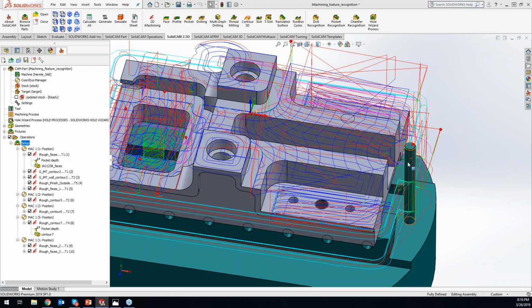Kevin, we got a quick question regarding the geometry definitions. If those can be used in other than iMachining operations like profile and pocket. Yes, you can, but only the contoured style. So if you're chaining something, yes, you can. I have not tried it with the actual faces itself. The only one that I would know that would be able to use the faces is either the pocket recognition or the pocket itself, because those are based off of the smart face technology that they've added in there. I would have to try that one out.